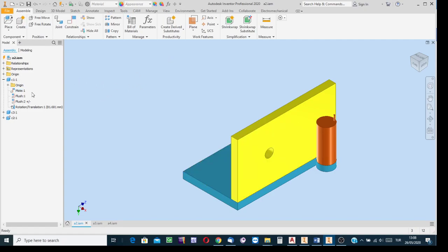And then understand how about the other. By the way, this is the icon that corresponds to the first component, and the cyan colored one is component 2. Since these two components have been related, if you drop the list of the constraint symbols, clicking on the associated cross, you can see, for instance, Mate 1. Since the same constraint is for relating this with respect to the other, the same icon with the same ID number and name will be in the list of the associated constraints for this component as well. Mate 1.